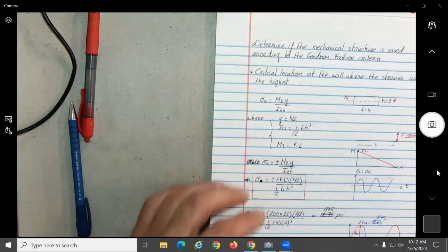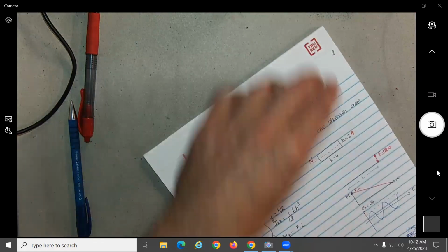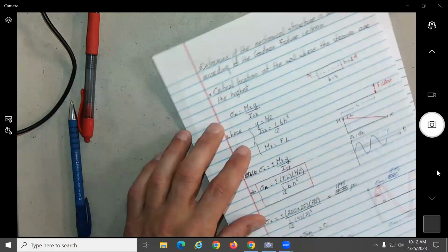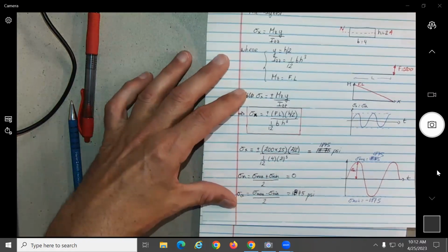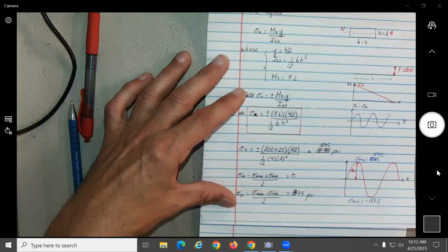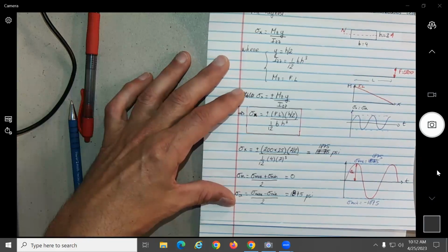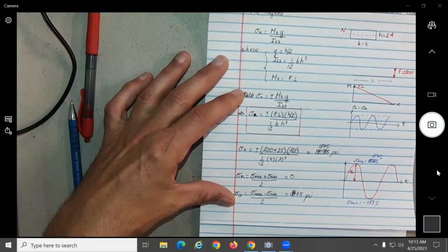All right, so here we go. In the stress calculation using the hole as part of the moment of inertia, does that mean you wouldn't need to do a stress concentration using the factor, if you were removing the diameter of the hole? Yes. That's basically what all this is doing.